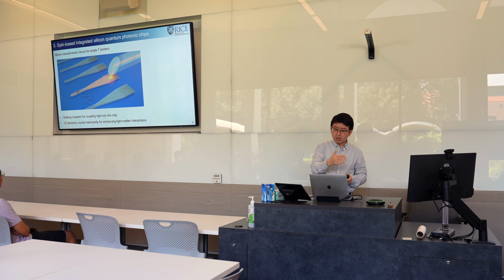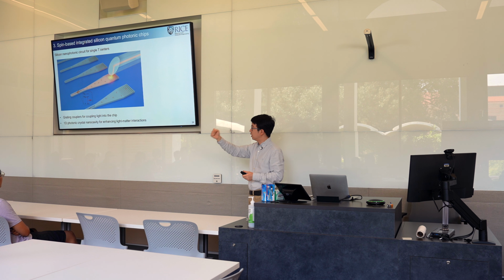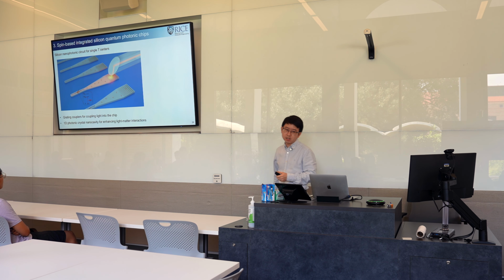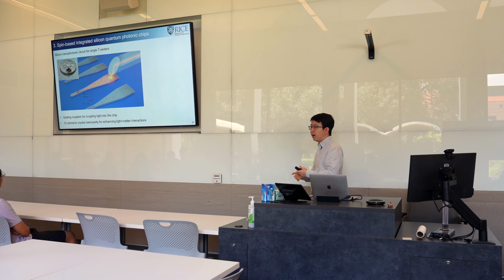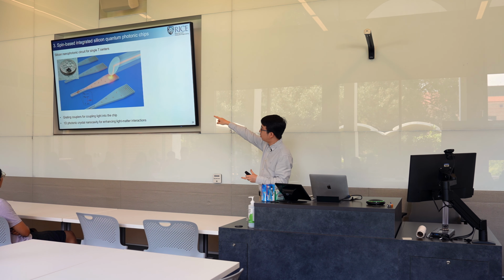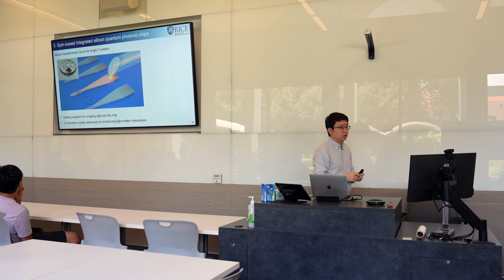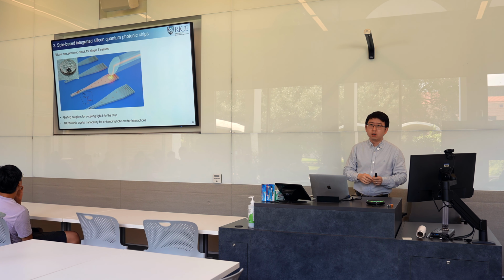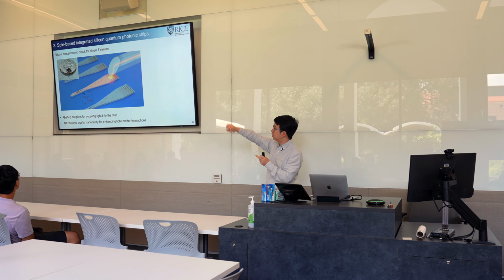Okay, and then on the other end of the device, you have this 1D photonic crystal, right? This series of holes on that 1D nanobeam. So that's our cavity. And because this is silicon photonics, you can do a large scale fabrication. Actually this small piece of silicon is 4.5 millimeter by 4.5 millimeter. We have about 120 devices on that line.